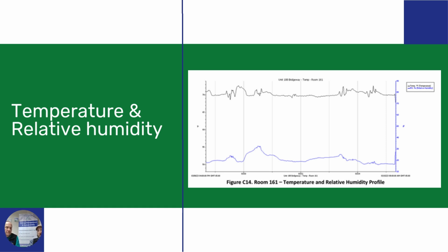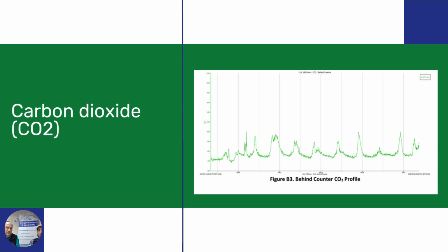This is a good indicator that the thermostat or the sensor that's controlling this area really isn't doing anything other than it's locked in on a single set point, seven days a week, 24 hours a day. And again, that's something that we wouldn't necessarily see, because if we walked up to the thermostat, we may see, oh gosh, it's set at 72. We don't know, are they really manually turning that down at night? Or is there a schedule working on that thermostat? This gives us the data to show us what's really happening there.